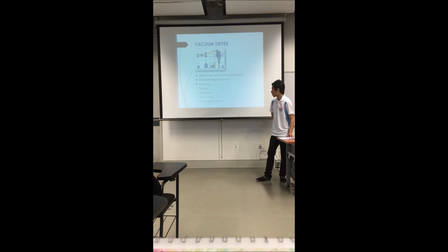As for the surface area, in a conical dryer, the surface area of the heated wall is less than proportional to the volume, so the drying time becomes faster in a smaller dryer. And lastly is the heat transfer coefficient. Heat transfer coefficient is a product-dependent parameter, but wet products tend to have a 4 to 6 times bigger heat transfer coefficient compared to dry material.